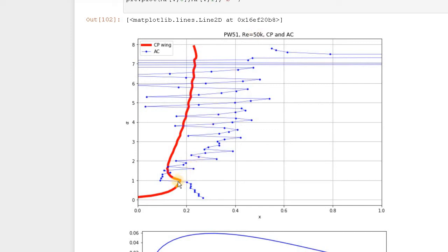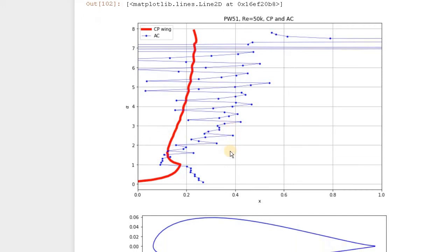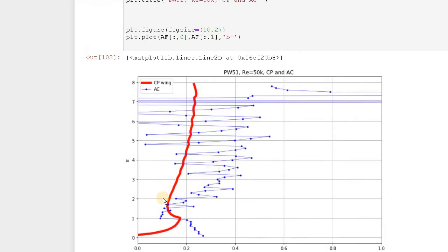But you might have some instability in this range, and then eventually you're going to have the pitch up moment, which will lead you to higher alphas. Then, because the curve again takes this shape from the nose to the tail, it's going to be stable. So it's going to be stable at maybe 2.5 degrees of angle of attack. So all is good for this airfoil except maybe this range. But I will talk about this later, how to fix this problem.